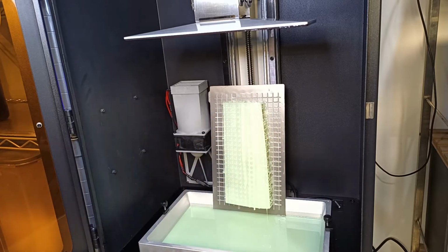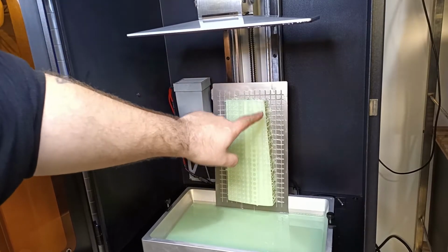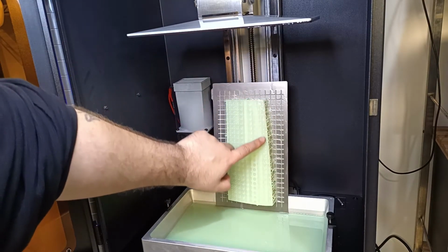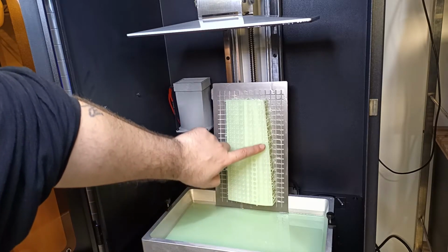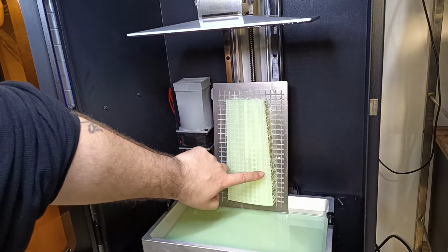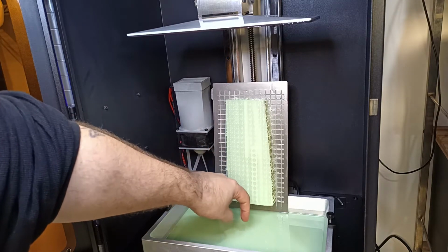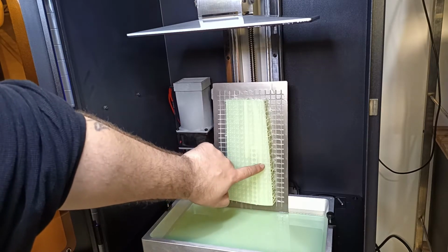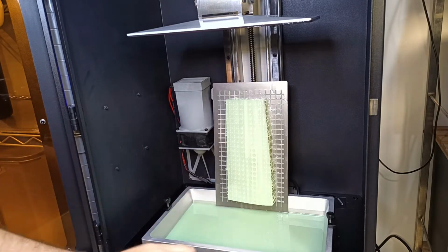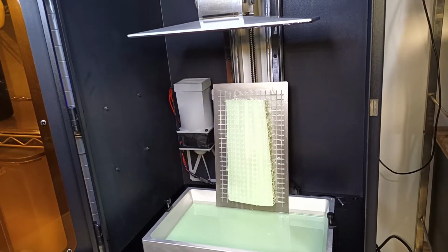And then I just let that sit and drain. So now there's much better print quality and print surface, both on the leading edge here and on this top surface. So this spot round about here is the highest point on the print. So this would be the last bit of the drain. So whatever the height of the resin in the vat is at the time when it prints this, that's the amount that will have pooled up in the inside here. So it's nothing to worry about with the weight of it pulling off the supports or anything like that.